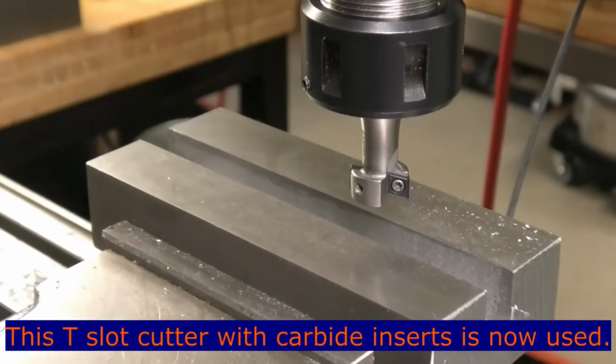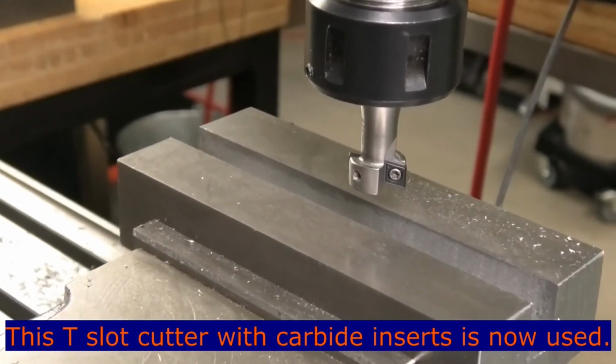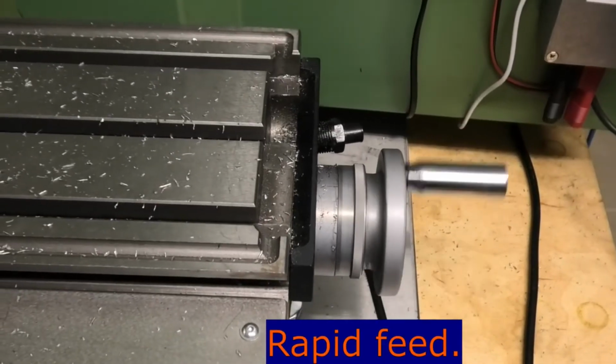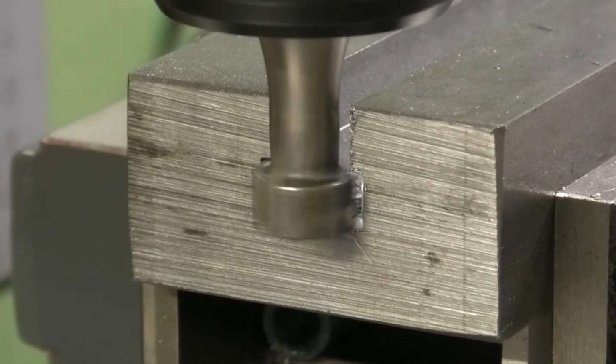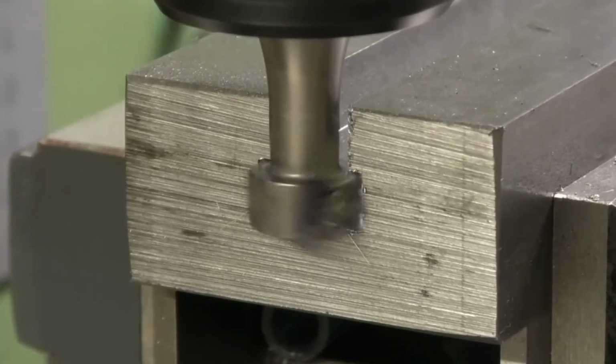This T-slot cutter with carbide inserts is now used. This carbide T-slot cutter was first used with a 16 mm ER25 collet. The torque could not be transmitted safely, so the milling cutter was then placed in a Weldon chuck.